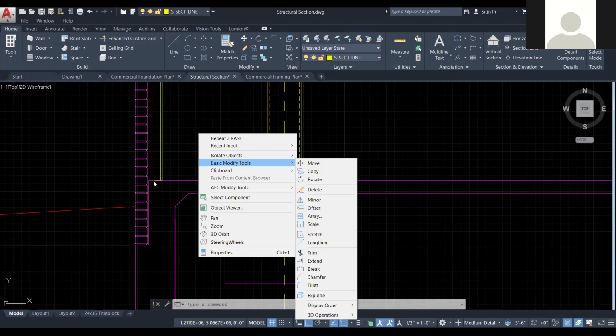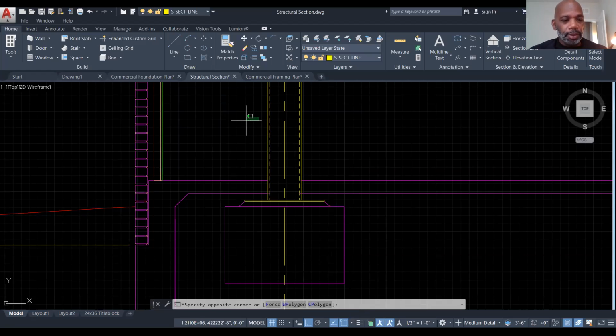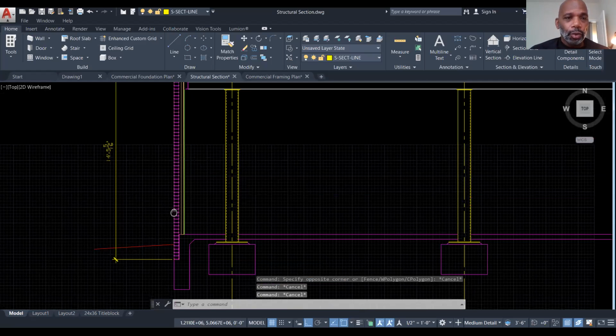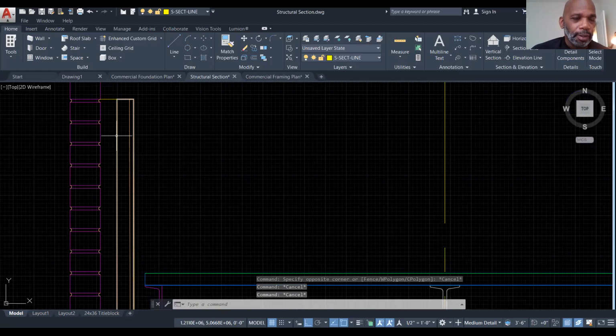The air gap is 3 7/8 inch. Well, no. It shouldn't be that. It should be 2 inches, right? 'Cause now listen. We started at the top here, right? Here's the brick veneer, and then this is 2 inches right here. This is the airspace.